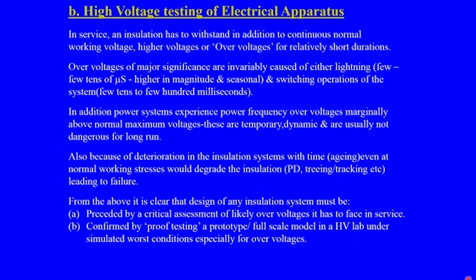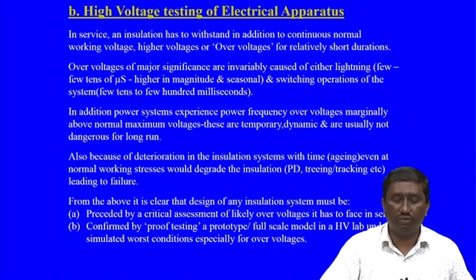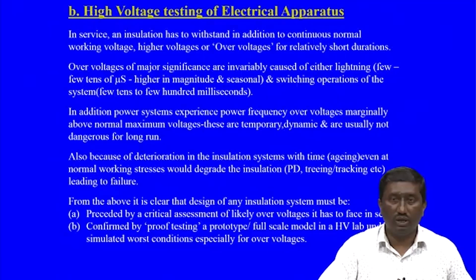This should be confirmed by proof testing, or in some cases a prototype or full scale model. So, depending upon the confirmation, this has to be carried out in a high voltage laboratory under the simulated worst conditions, particularly for over voltages.